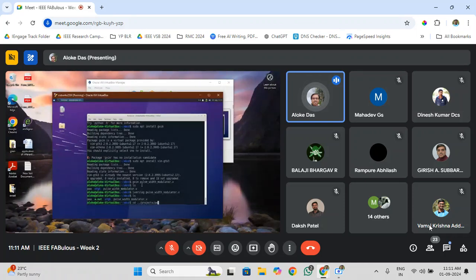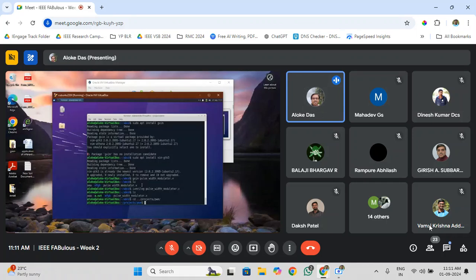PWM. This is the latest IP I have written. I have given this project to many institutes, many people. Nobody could give me the output, but this is very simple. Pulse width modulator is a technique, a design, to modulate the pulse width. The frequency of the clock doesn't change. The time period remains the same, but the uptime and downtime vary. In the digital world, it is all square wave. The clock signal is high for some time, then low for some time within one time period.